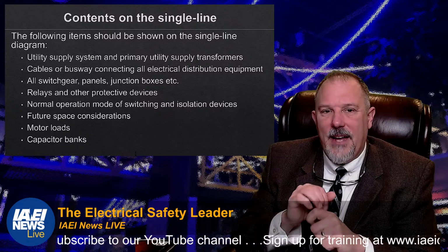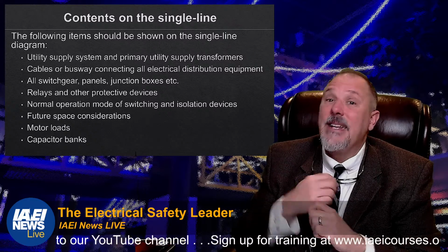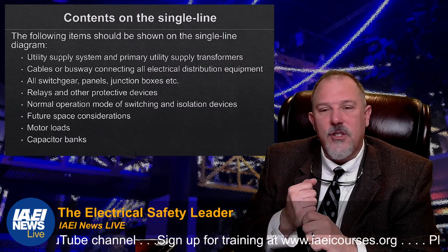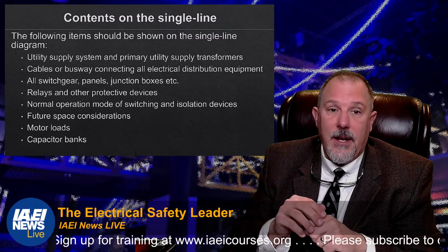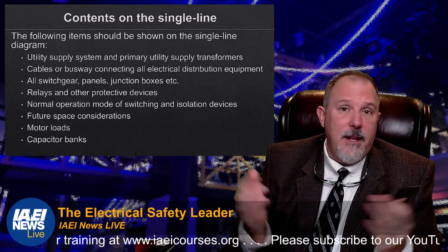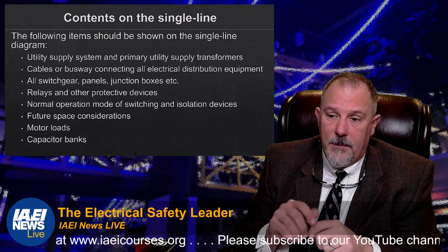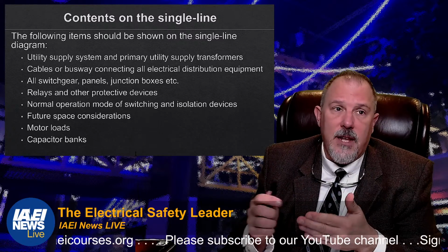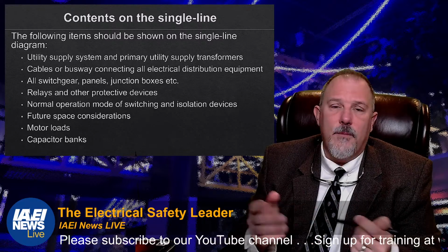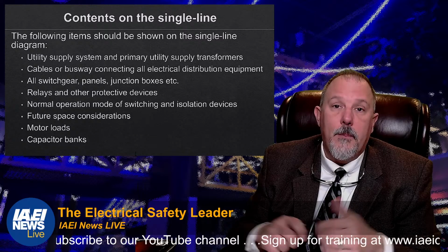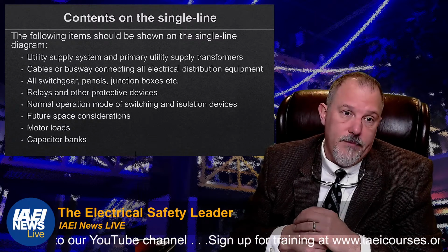I don't know. I've seen people go both ways in that. I never put junction boxes in my one-line diagrams. That was for the electrician. And the reason, it didn't add any impedance. And typically, any junction boxes that were planned, that's not something I'm going out to bid for. That's going to be purchased as we go.